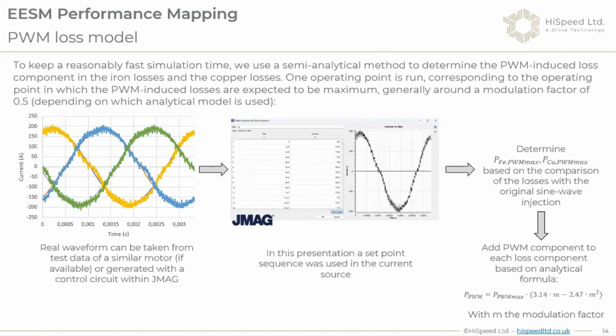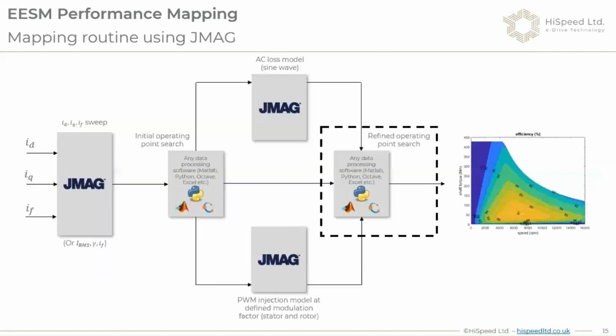This is the last part which we implement in the process. Once we have all the data, if you start from the beginning, we have the flux linkages, the electromagnetic torque, the iron losses created by the fundamental harmonic, and all the AC loss components. By the way, the AC loss components we do extend into 3D, but by means of analytical equations again. We're not going to create a 3D model to simulate this simply because it takes too much time. So we use that analytical equation to expand the AC losses into the end windings, which will be a lower proportion, of course, compared to what you have throughout the stack. We add the losses induced by the PWM switching, and then we process again with all these losses. And this is where really all the losses come into the equation.